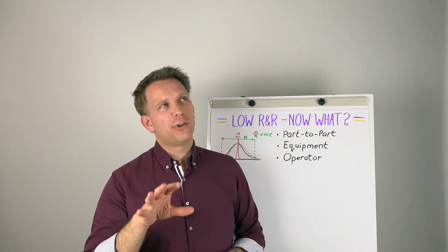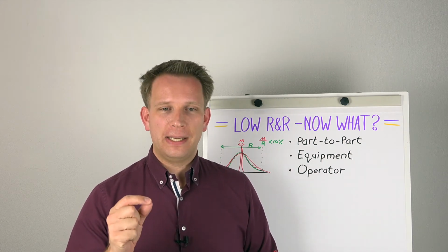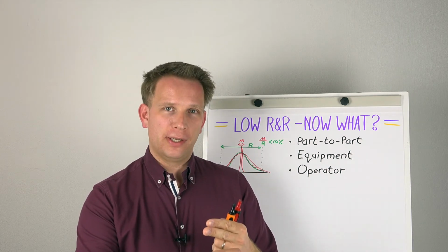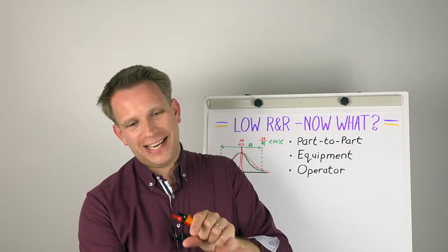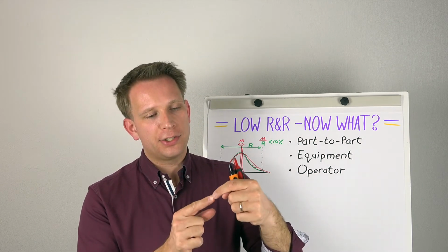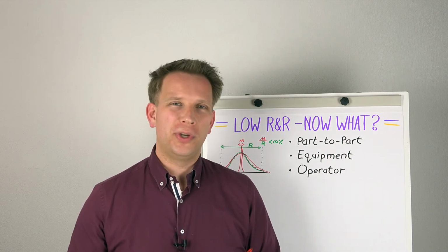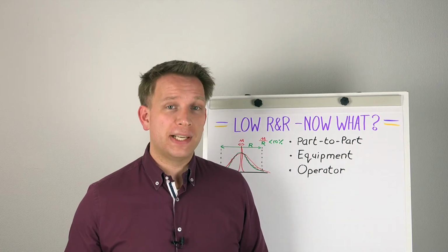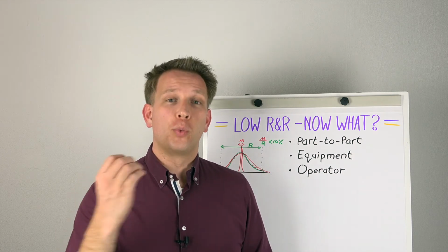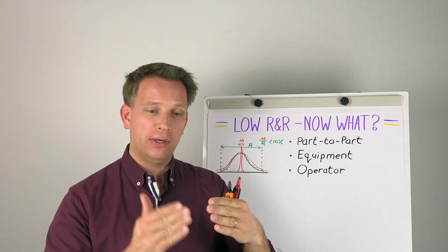Now, then, well, easy to read, there we actually have the other thing with these calipers, and that is if you have the traditional ones, where you basically read the millimeters on the main scale, and then on a secondary scale you can read those tenths of millimeters by checking which of the lines actually really match, and then the next one doesn't completely match. That system, you need to know what you're doing. I mean, for engineers, this is one of the things that we are sort of proud of, that we know, but we learned it in school, wherever we learned it. This is not a natural way of reading exactly what your tenth or hundredth of a millimeter is.